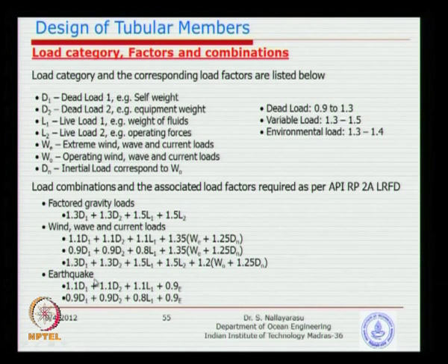Similarly, for earthquake condition, the reduced factor of 1.1 rather than 1.3. So, that is the advantage of giving variable load factors for different scenarios, not only for different loads, but different scenarios of loading. Among here you can see there are two types of dead loads. One is a fixed dead load, basically self weight or structure weight.